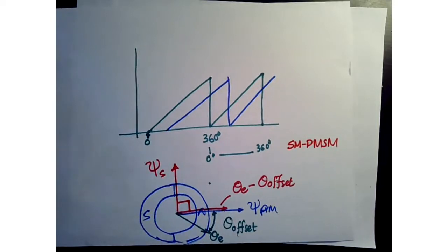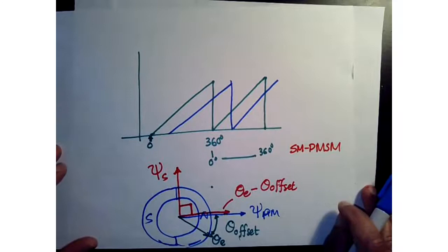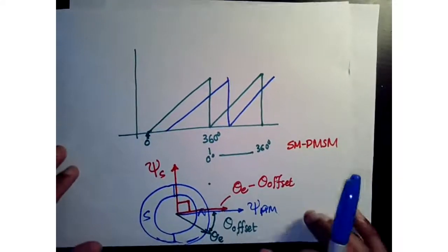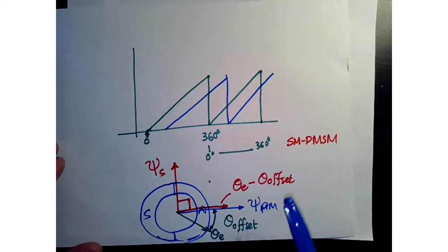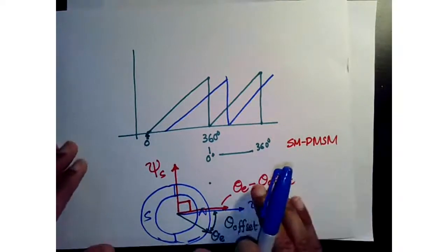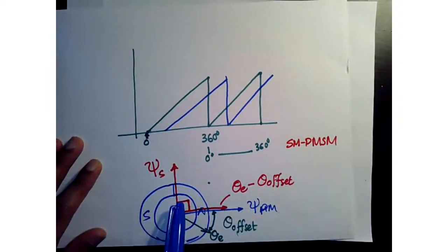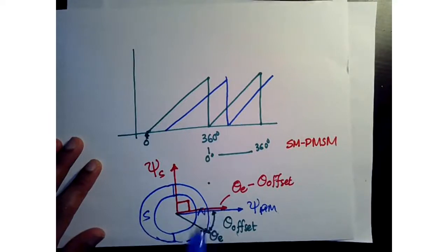And of course, guess what? Like everything else, the devil is in the details. So you have to pay attention to details, and then how do we implement this? How do we achieve this? There's a lot of science that goes into trying to orient the stator flux 90 degrees out of the rotor flux. So let's draw a little block diagram here, and I'll try to explain what we do from a control algorithm perspective. This is the FOC algorithm.